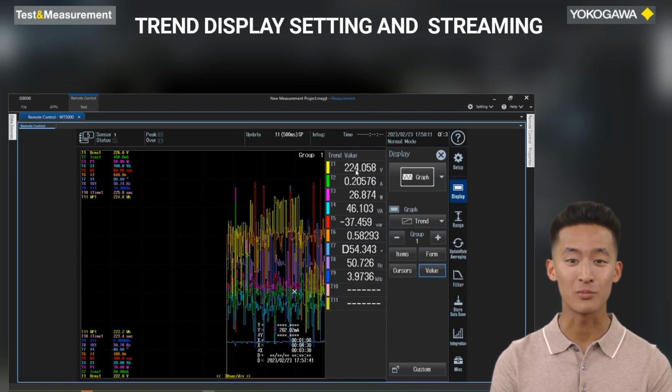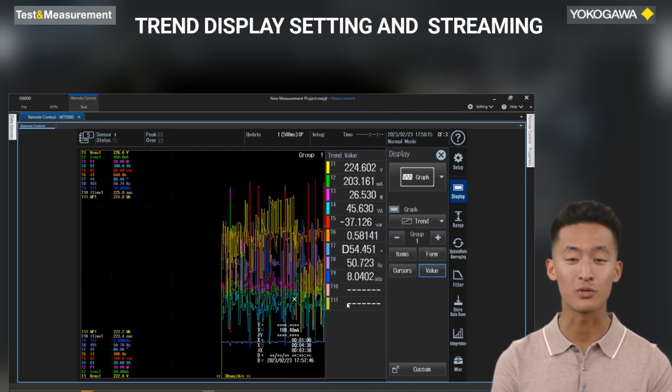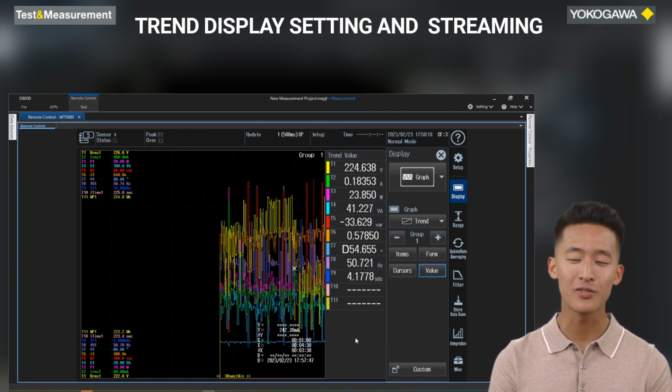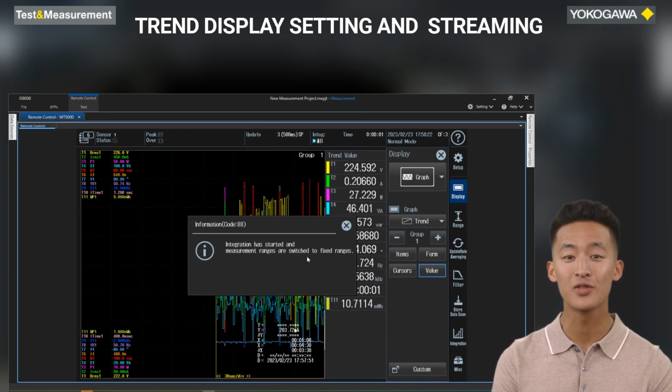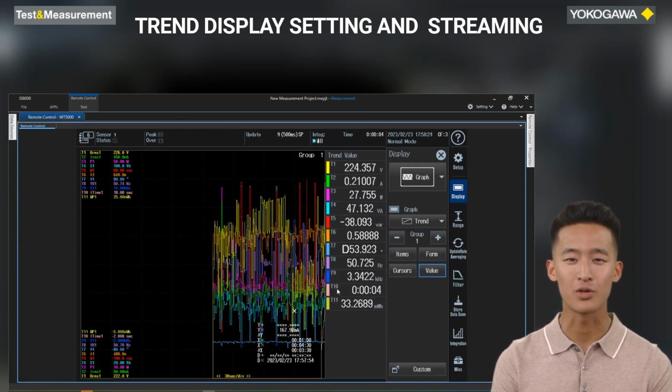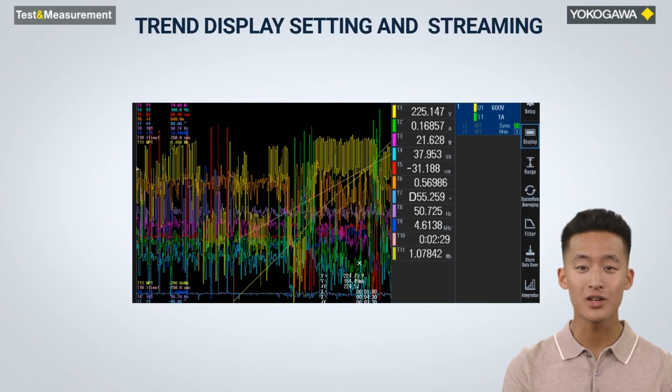Now for displaying the moving values of trend graph, click on values, which will display the moving values of trend graph in WT5000 display. Since we have configured for integration time and energy, we will switch on integration function to get values for trace 10 and trace 11. As we can see on the screen, trend display is a very powerful tool to analyze the measurement data over the time, and with this user can have a very clear understanding of behavior of parameters over the time.